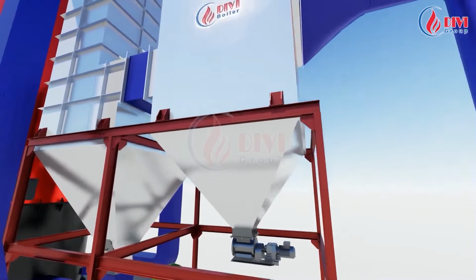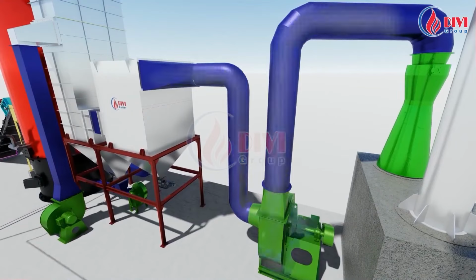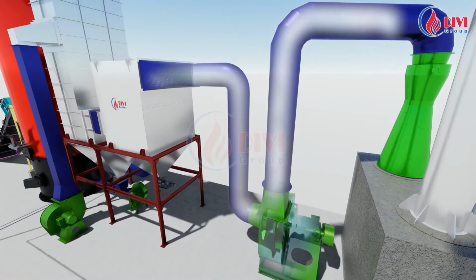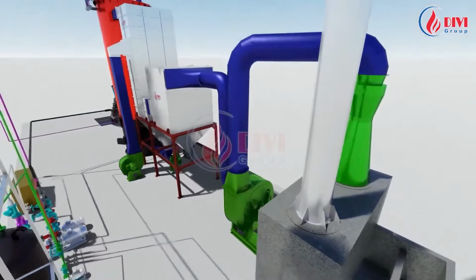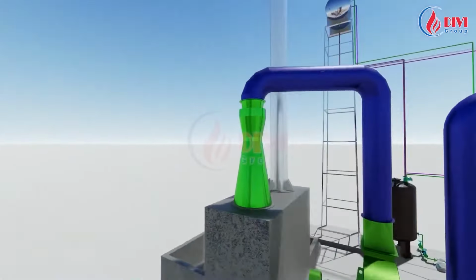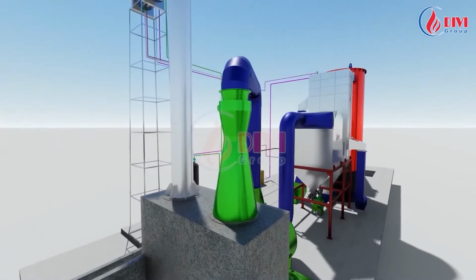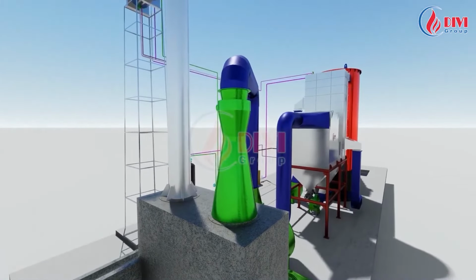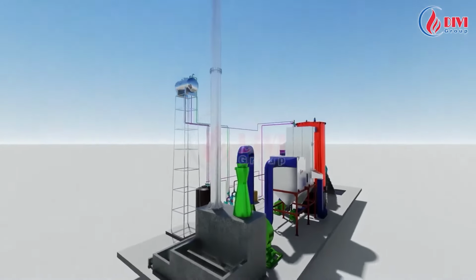The exhaust fan system will help the smoke flow from the furnace to pass through the body of the thermal oil heater and through the equipment in the rear part of the thermal oil heater. The water scrubber tank will help to recover all the ash remaining in the exhaust smoke by spraying water to wash the smoke stream with the Venturi nozzle. Here, 100% of the ash will be completely recovered before being discharged into the environment. Finally, clean smoke is discharged into the environment by a chimney.